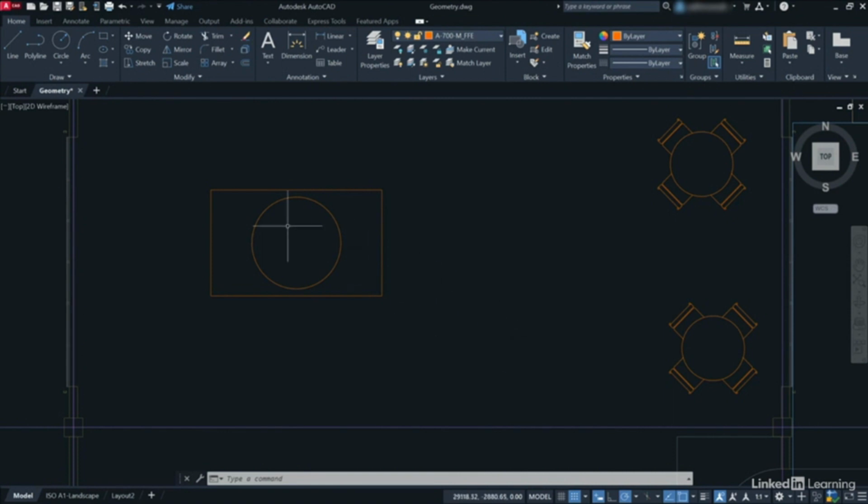So I'm going to go over to the line command here in the draw panel. So there's the line command there. Click on the line command, come into the drawing area, and it's prompting for your first point. Now, I'm not worried about exact coordinates here at all. You just need to pick a point about where my crosshair is there, near your other table, in the space, in the floor plan. So it's a left click. Now, we're going to use polar tracking first before we think about orthogonal, ortho.